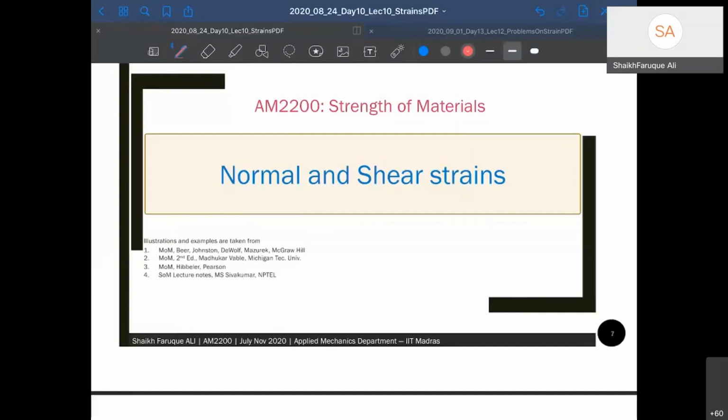Understanding of deformations, and we have also given some basic things like there can be rotation and there can be elongation. These are the two kinds of things that we get in deformation, right? So these are all elastic rotations and elastic elongations. I'm not talking about rigid bodies here right now. Okay. So those two things give rise to something called normal strain and shear strain. We will now understand what normal strain and shear strain are.